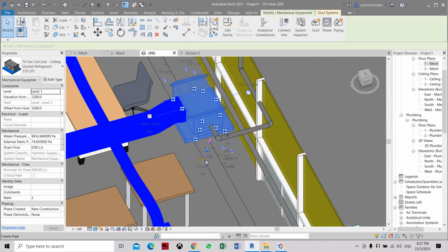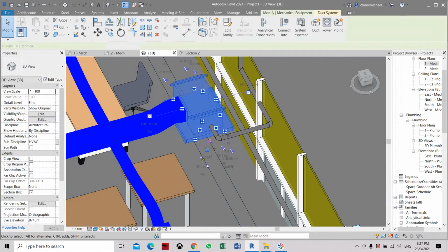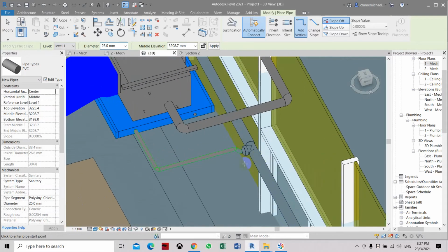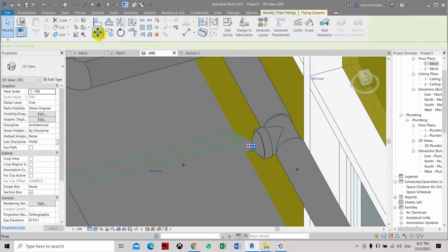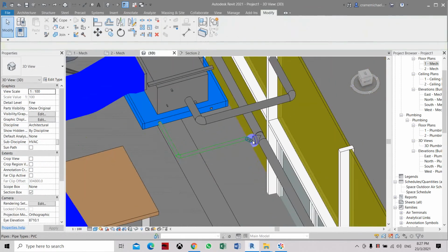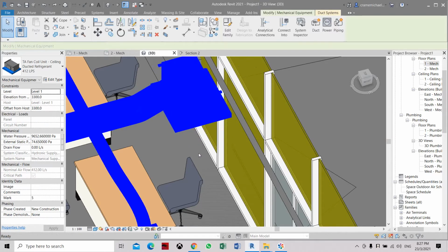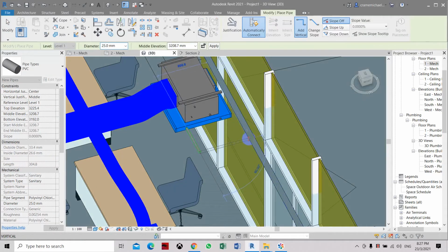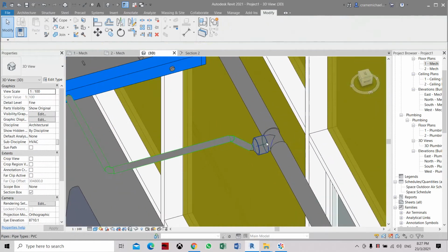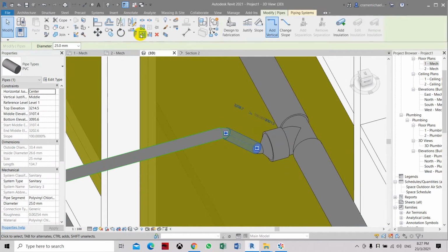Here we can also do the same. Actually, you can select here, select on 3D, select here 25, and connect it. You can move the offset if you want away from the connection, so it looks much better. So later we'll arrange this, but we'll use it at 45. Then we'll connect another drainage pipe here, and let's connect it. So here you can see that the pipe has a reducer from 40 to 25 mm, and then immediately we offset. So let's move this.